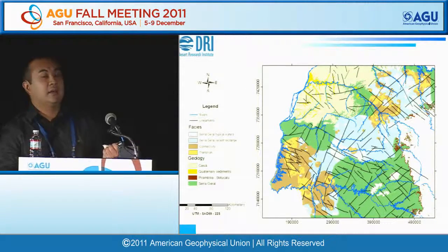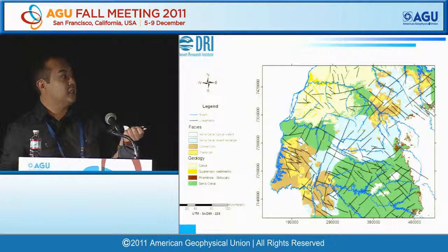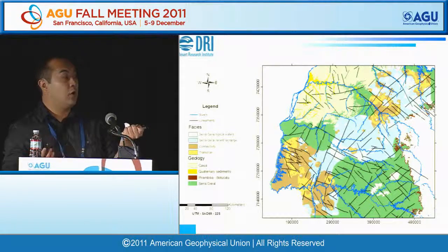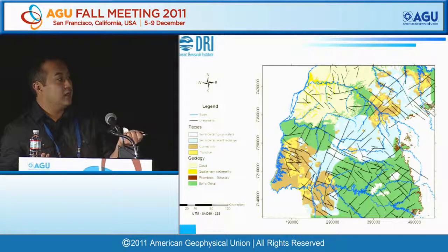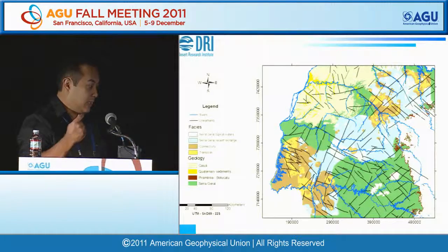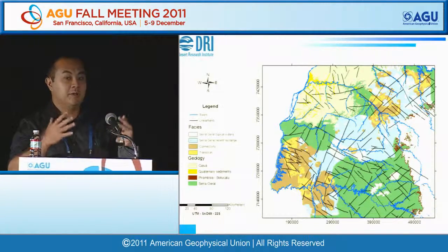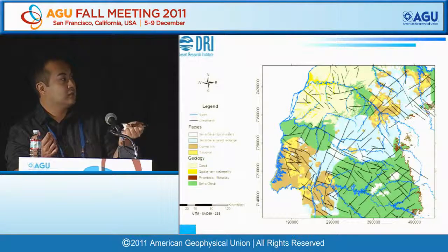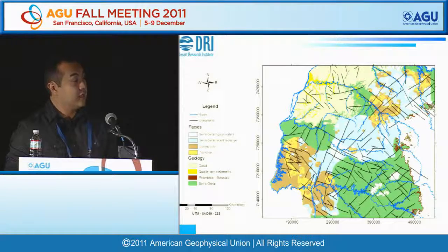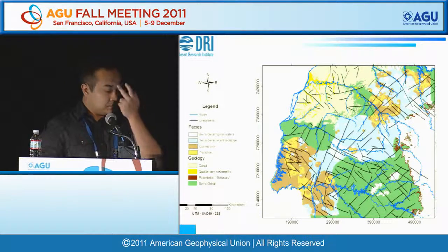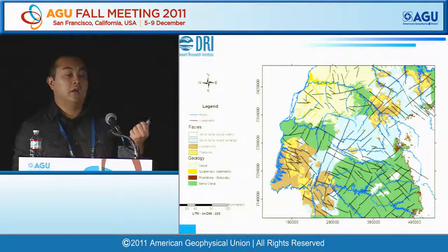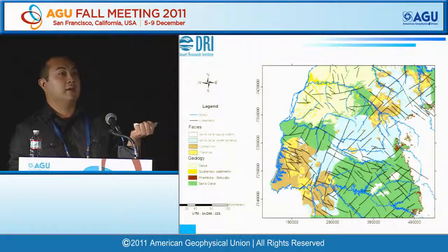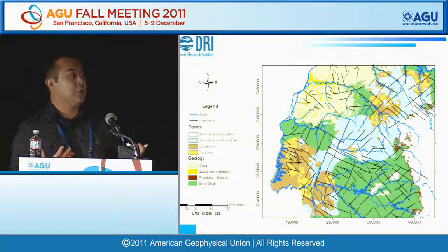And this map summarizes the result after the K-means clustering classification, showing the typical waters for Serra Geral or recent recharge waters, transition areas where we will have both signatures, Serra Geral and Guarani Aquifer, and what will be more typical for the Guarani Aquifer in this region over here. It also agrees with previous studies where the connection will be more driven by structures, and with other studies that were investigating these connections between the aquifers.